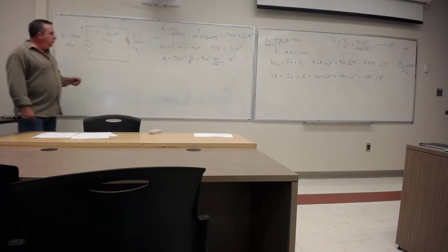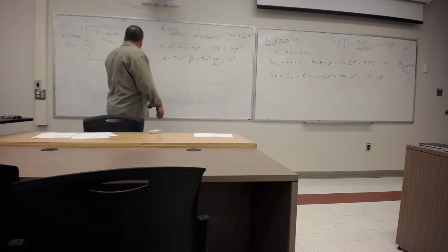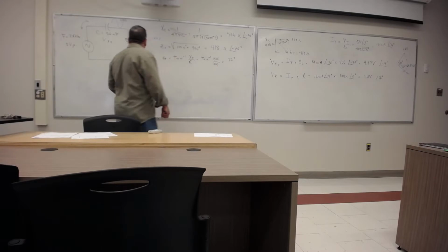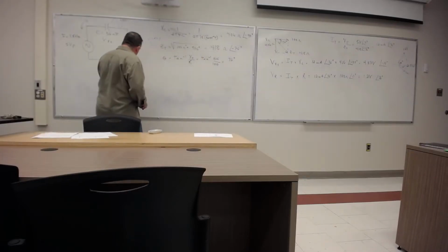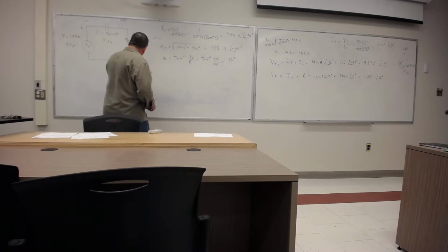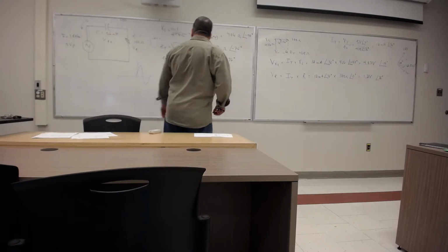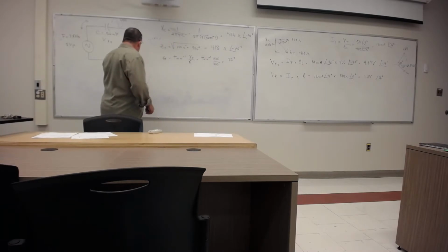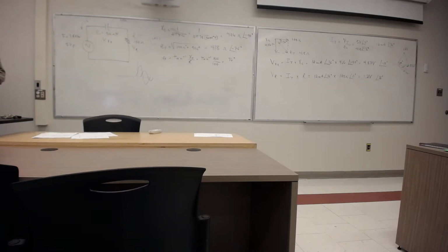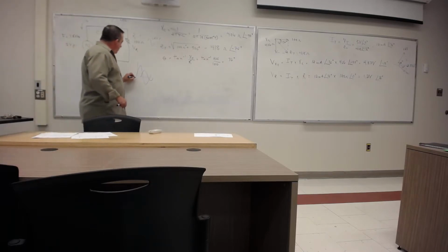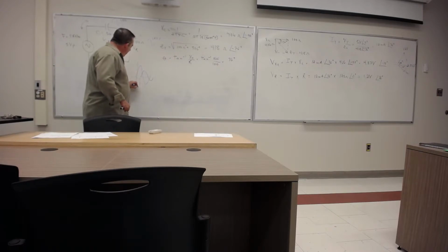Okay? So if you're going to look on an oscilloscope, what you would see is VXC, which is at negative 14 degrees. So VXC would be like over here. And then you would have VR, which would be, let's say this is 90, somewhere like this. You'd have 2 sine waves. They're out of phase with each other. One would be at negative 14, lagging, and the other one would be at plus 76, leading.